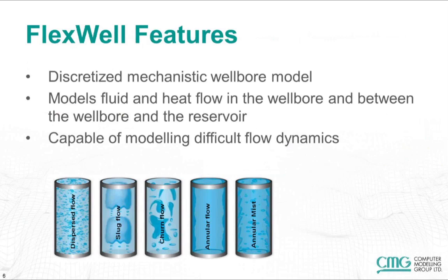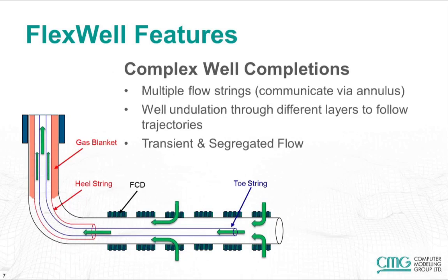In STARS, in addition to the source-sink model, we also have the FlexWell model. FlexWell is a discretized mechanistic wellbore model that is coupled to a reservoir model, and it models the fluid and heat flow in the wellbore and in between the wellbore and the reservoir. And within it is incorporated the physics to be able to capture the complex flow dynamics that we see in the field.